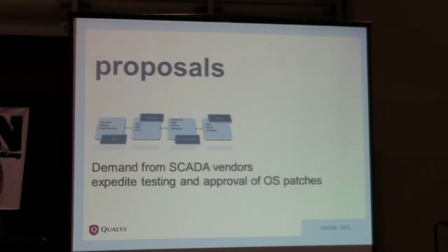Also demand from your SCADA vendors, in the contract and in writing, that they will give you guidance on patching. They will test those patches first and then tell you if the patch is safe or not to apply.